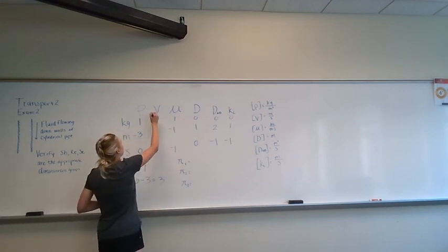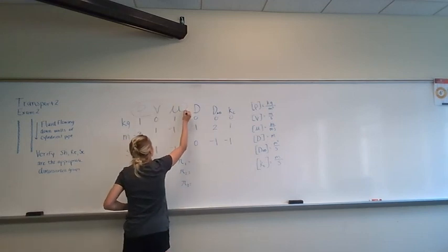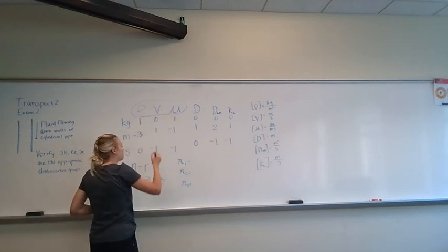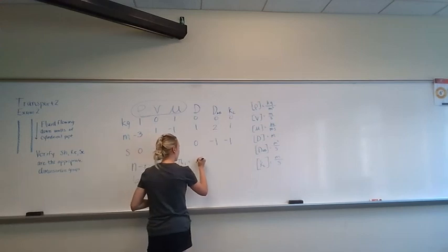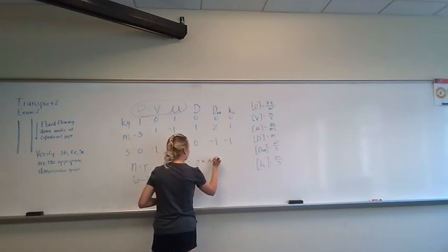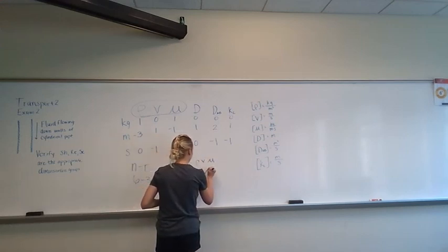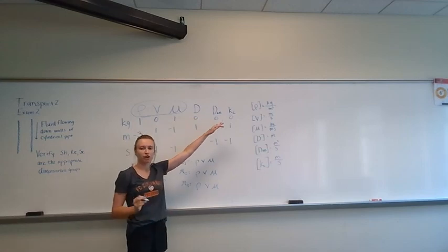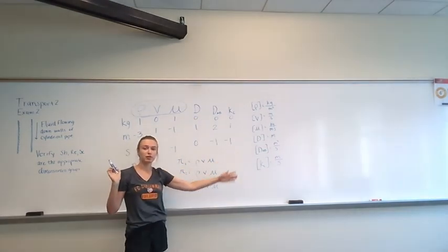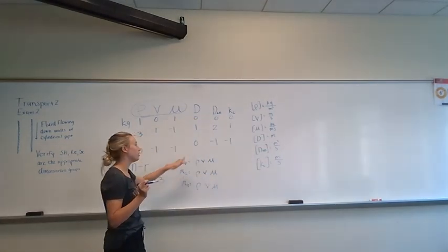So I'm just going to choose density, velocity, and viscosity as the core group, and I will write this in each of the 3 equations. So density, velocity, viscosity, density, velocity, viscosity, density, velocity, viscosity. And then these 3 remaining parameters are called the non-core group of parameters, and we will divide these among the 3 equations.